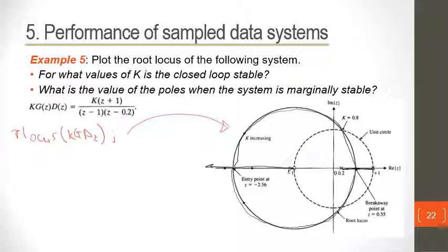If you look at the location of the root locus on the real axis, it is here because it's on the left of one pole. It's not here because there are 2 poles here, so it's on the left of 2 poles. So the root locus is not there, but the root locus is here. And on the left of the 3 of them, 1, 2, 3, it's also there. You can see that because it is a second order system, the arcs are circular, much the same way as the root locus drawing method that we have used previously. And so we can calculate that.